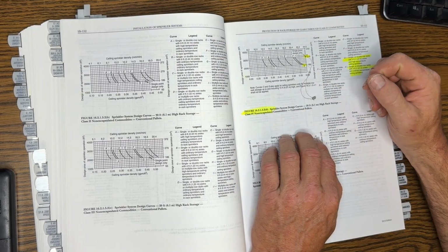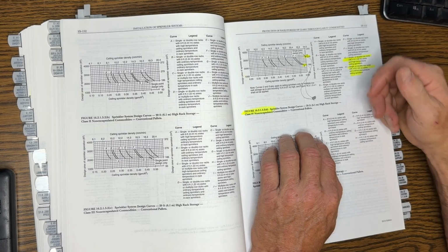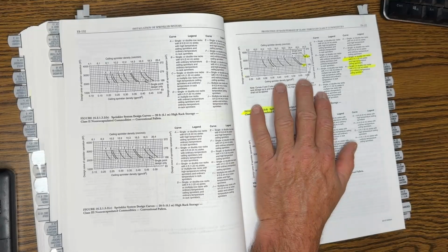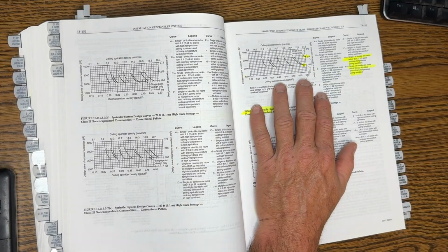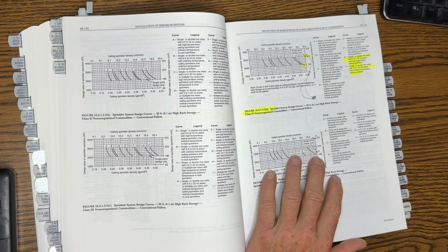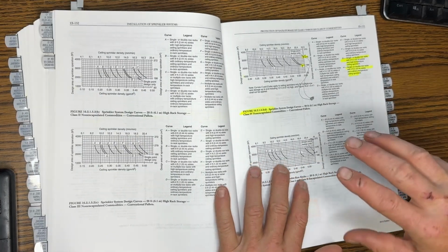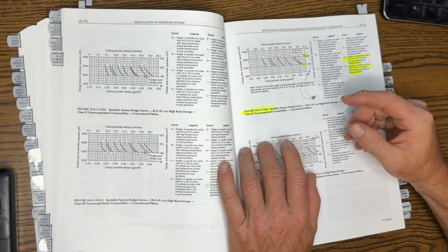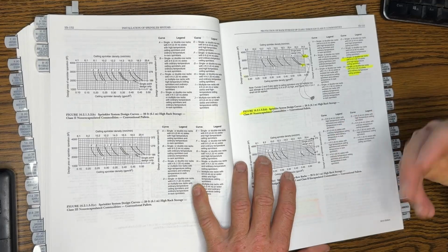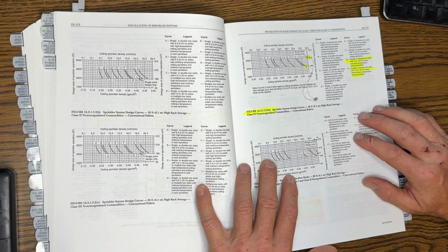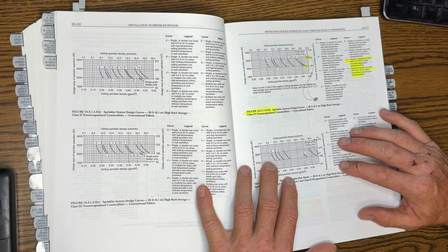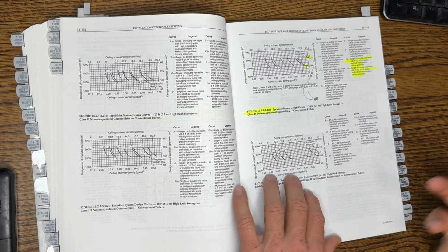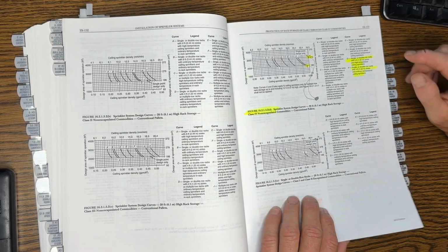It was 0.6 GPM per square foot at 3,000 square foot design flow, with high temp heads. Or it gives you some other options. You can go 0.58 GPM per square foot at 2,000 square feet with ordinary temp heads. The high heat heads delay activation. That's the principle. It takes longer to activate, which means a fire can get bigger. But if you're worried about a heater or sunlight activating your heads, you have to go with a high temp, which means you have to provide a bigger design area and more flow to control the fire that was permitted to grow bigger because of the delay. So that's the principle behind it.